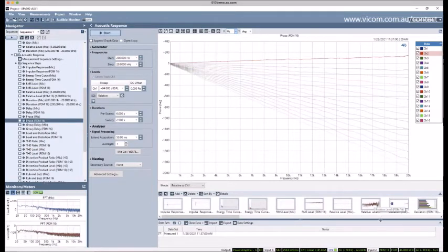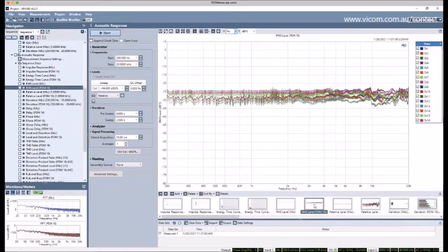And again, since I have calibrated the sound source to give us 1 Pascal at the reference position, I could, in theory, directly measure the sensitivity right here, right? Particularly if we look at channel 2, right? That is channel 2 is where the reference microphone is parallel to or aligned to. So I can see, oh yeah, I'm getting right about minus 26 or 25 dBFS per Pascal. But I can actually do the same trick I showed you with the Rms level meter result.